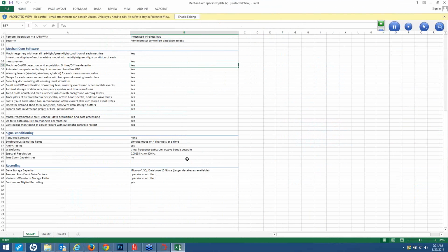You've only got a few seconds to grab a snapshot of data, and it's extremely difficult to set any kind of alarms on those things. Absolutely, I agree. Because if you're looking for something, the other part of it is that I like to look at the frequency spectra of the vibration, and of the current, like motor current signature analysis. Sure, and we can get that in there also.